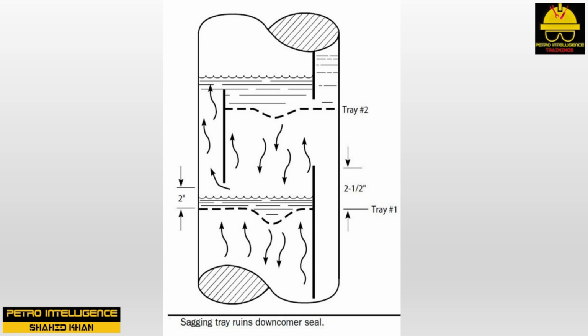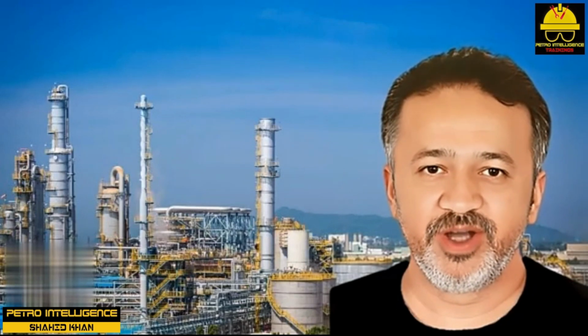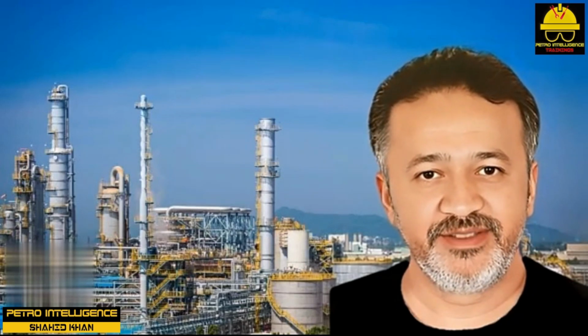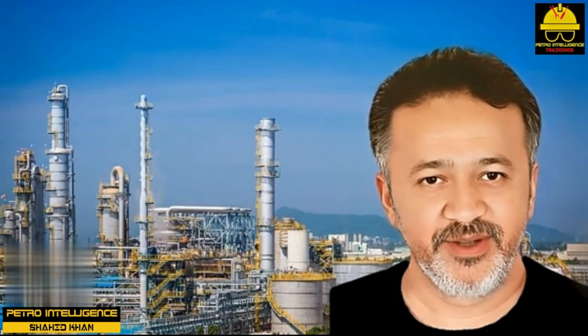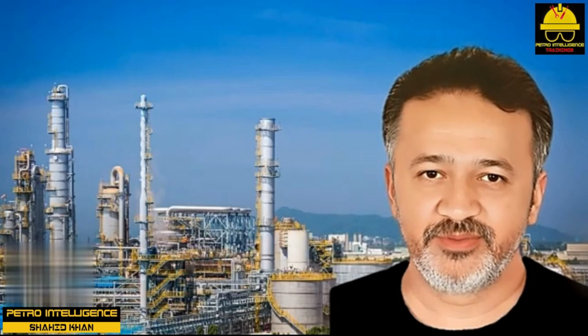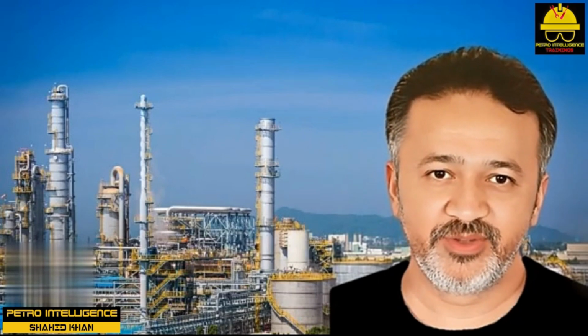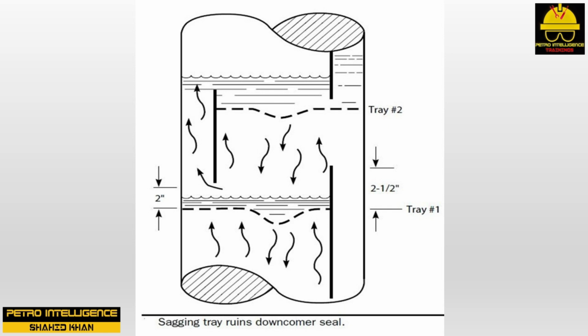6. Tray 2 will now start to weep, with the weeping concentrated on the low area of the tray. 7. Tray 2 now has most of its vapor feed flowing up through its outlet downcomer, rather than the tray deck, and most of its liquid flow is leaking through its tray deck. The net result of this unpleasant scenario is loss of both vapor-liquid contacting and tray efficiency. Note how mechanical problems like levelness of tray 1 ruin the tray efficiency of both trays 1 and 2.